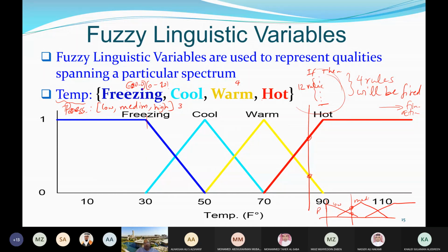As we mentioned, we have different stages. What we are doing here exactly is the fuzzification process. Now we convert from numerical values of the temperature, which is, for example, 85 degrees, and the pressure here 1 bar, 2 bar, 3 bar, so this is 3 bar for example.